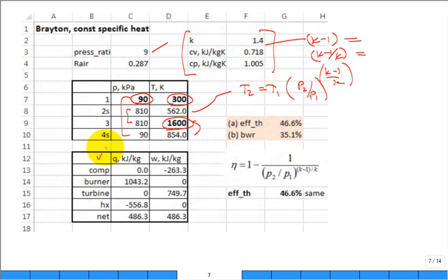Here is the table of all of the heat transfers and work transfers. Why is there a per kilogram on these terms? Yeah, it's per unit kilogram that flows through the device. Would it be the same as the Q dot in the burner divided by the mass flow rate of air through the burner? Yeah, that's exactly what that lowercase q of the burner is.